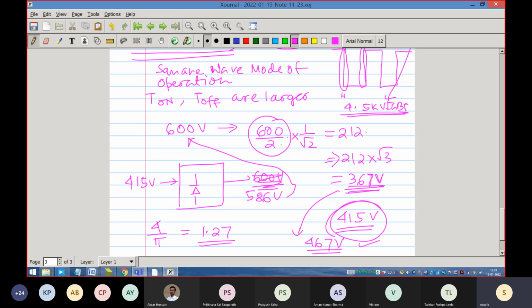Okay. But then if we give a square wave to the induction machine, then its characteristics will also be affected, and hence the feedback path also. No, the machine is AC, it does require AC. No, fundamentally you are giving AC. A square wave is also AC, but its characteristics mean, as I told you now, that it will be performing with a lot of pulsating torque, because this current is not good. I can analyze that in some class.